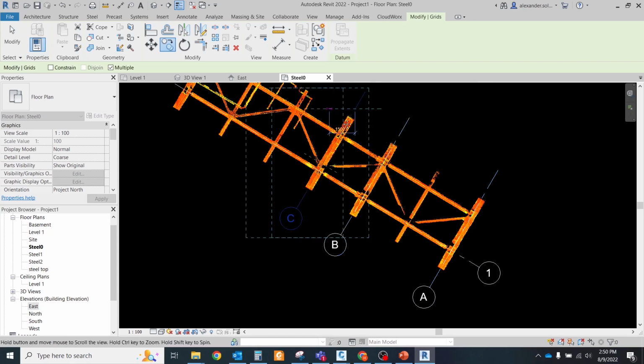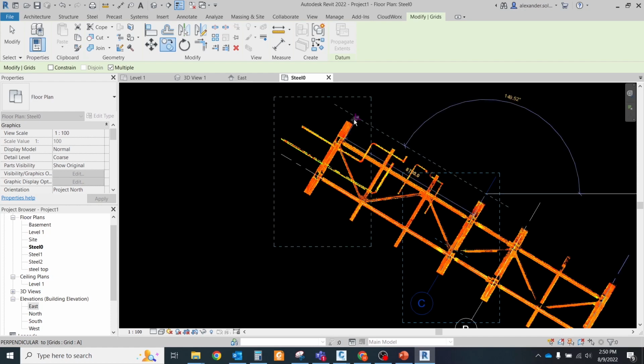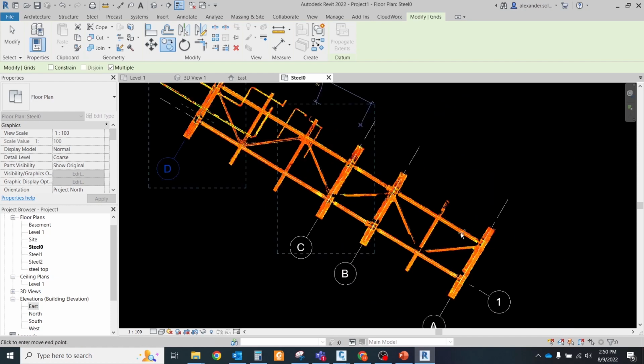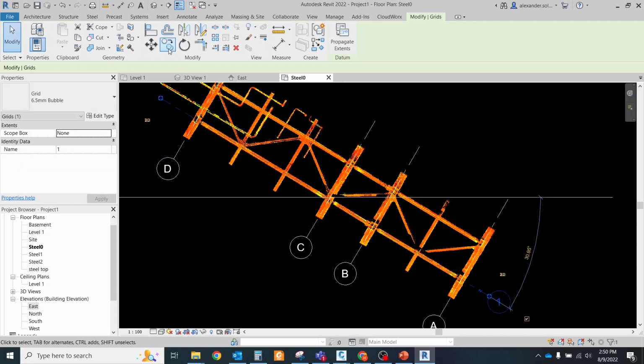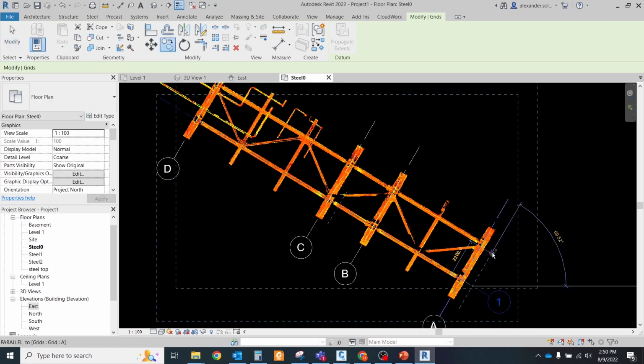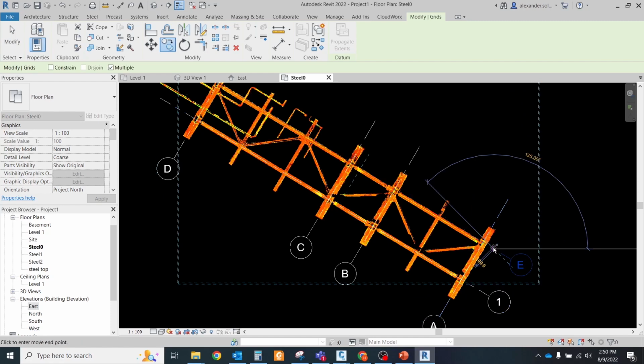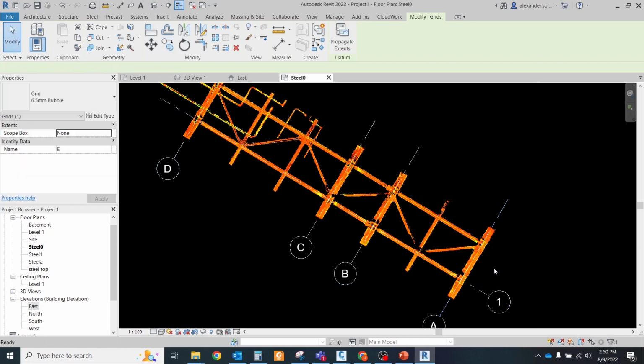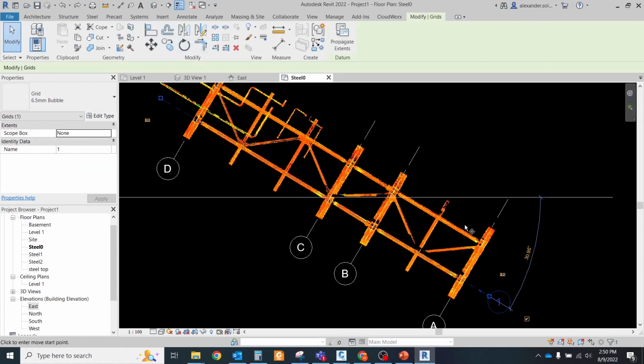The grid line tool works very well when you have a clean point cloud with the required elements that can be used to extract patches, but in many cases there are too many obstacles that prevent you from using it correctly. In this case, you must draw this axis manually, but before that I recommend you rotate your point cloud if the position of the main elements is different from the X and Y axis.